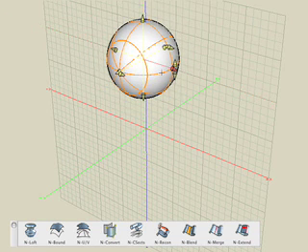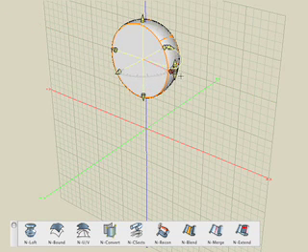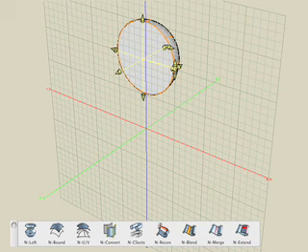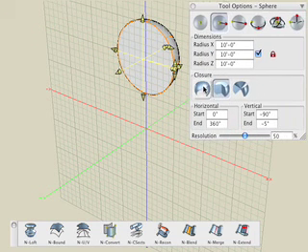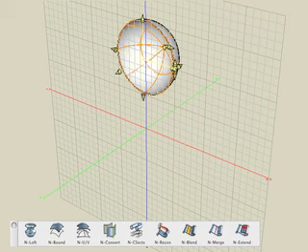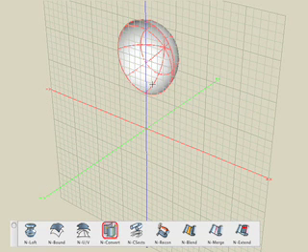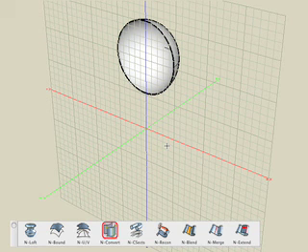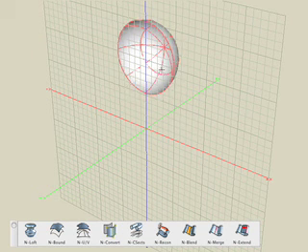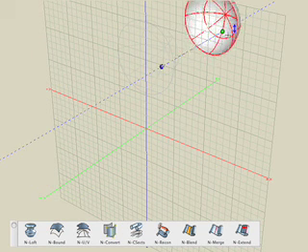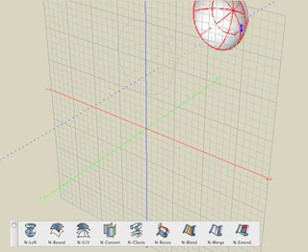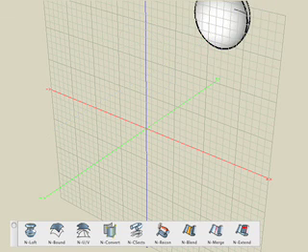Then we'll open the sphere 90 degrees. And then in the Tool Options palette, we can set the closure to be none to make it a surface object. Now let's use the Nurbs Convert tool and click on it to convert it into a Nurbs object. Then using the Move tool, and being sure we set the Copy modifier to be Self, we'll just move it back into the scene where we need it.